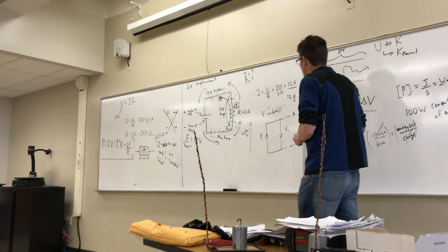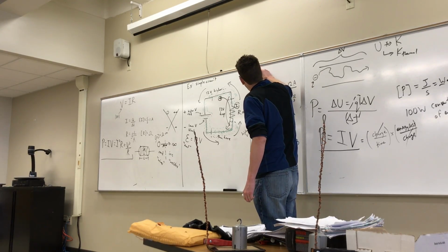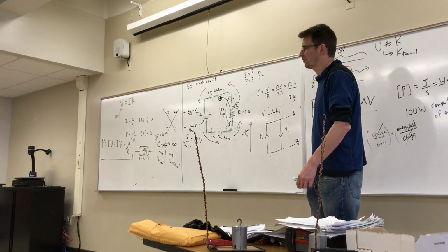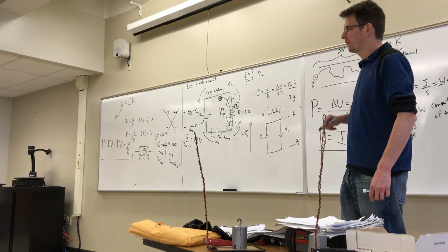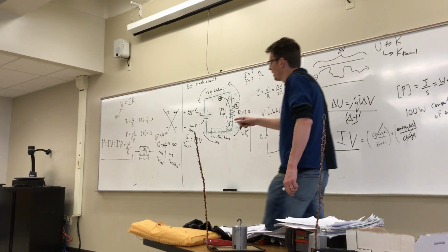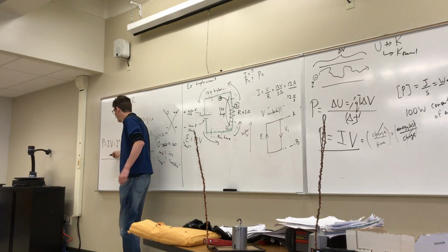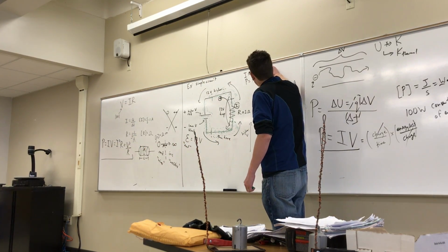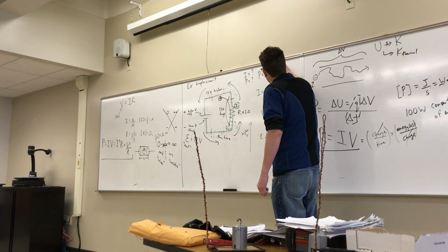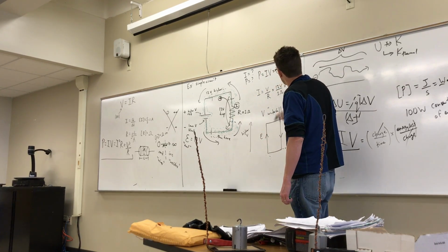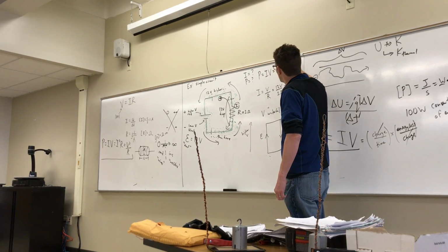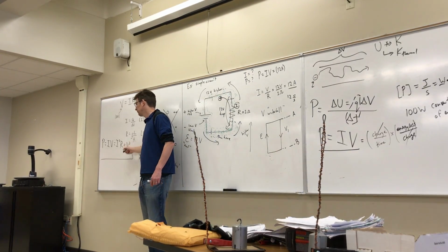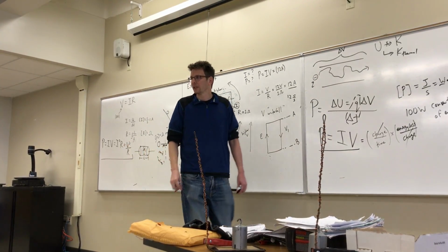Okay, so let's knock out the power here as well. I have any number of choices there. It doesn't really matter. This circuit is so simple, there's no real advantage to choosing any one of the three forms of the power law. We just pick one. Let's choose the first one, I times V. The current we found was 12 amps. I guess the compelling reason to use the last one is that it's using given information, just in case we calculated the current wrong.